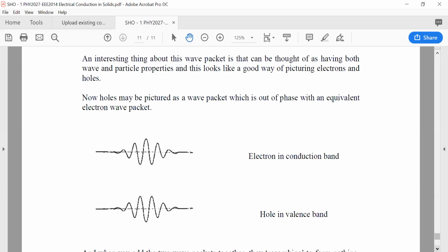For example, we know the effective mass of a hole is considerably greater than the effective mass of an electron. In both cases, their effective mass is unlike the rest mass of free space, and we've got the data for that. But when you bring these small matter together, they behave differently. So if you have lots of electrons, they don't behave as if they're individual electrons, and vice versa. In fact, their effective masses are different in different parts of the energy bands, and there are different longitudinal and transverse effective masses as well. These masses are listed on your data sheet for some of the materials.